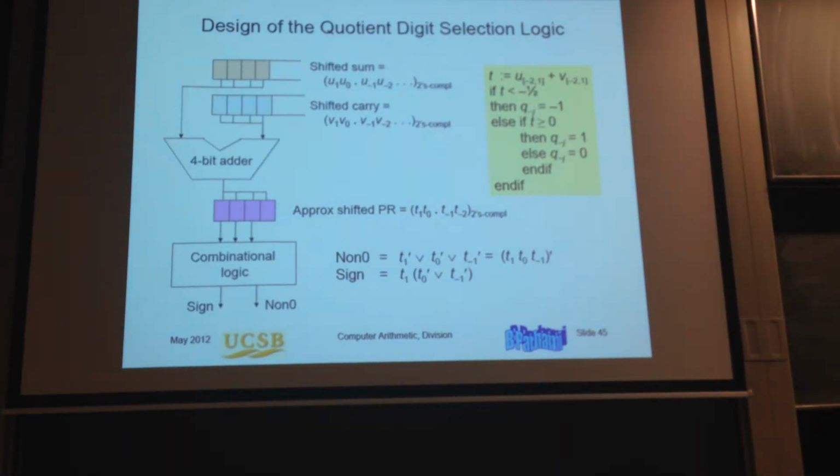Now this is a revisit on how you do the calculation. I don't know why this slide is here, it should have been earlier, but anyway, good that it's here. This is about that inspection that we have for using carry-save adders. I'm doing an addition, and then based on the result and some combinational logic, I decide if it's 0 or not, which is the sign. I would expect that in practice I will not implement it like that. I will just make a lookup table, which would most likely be faster.